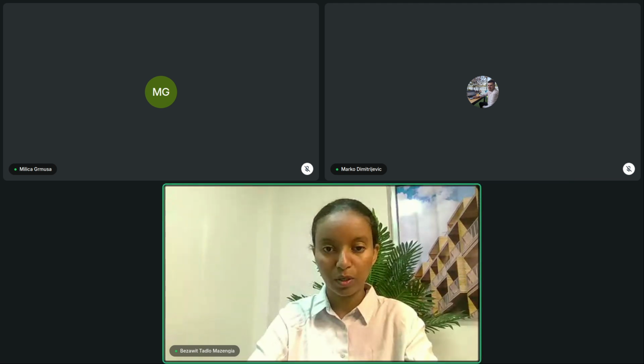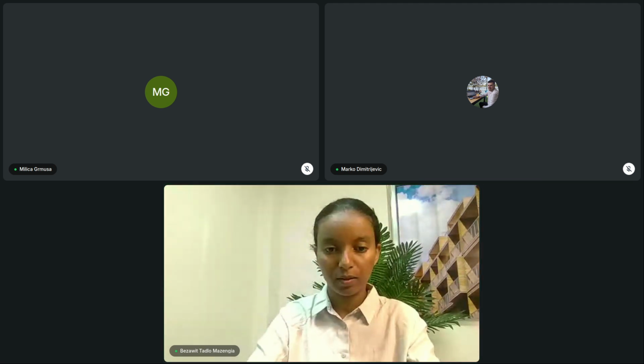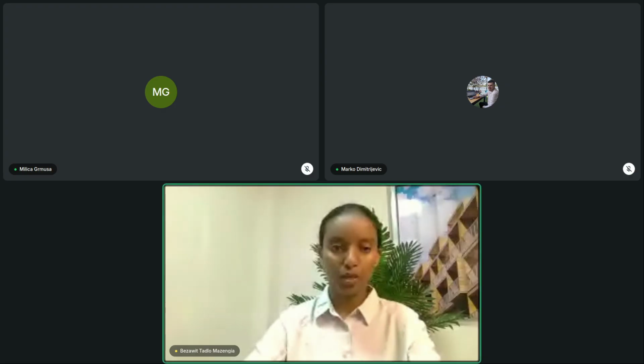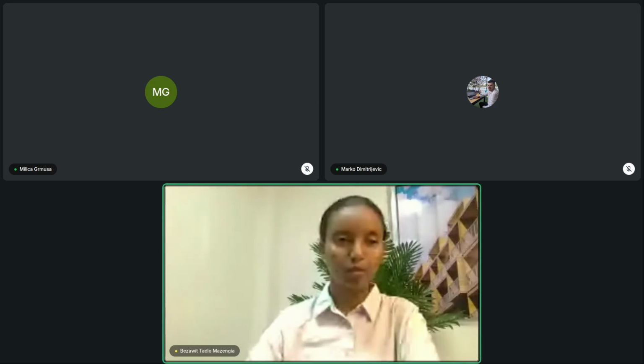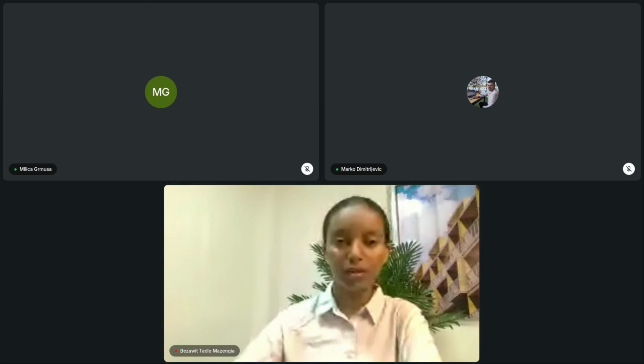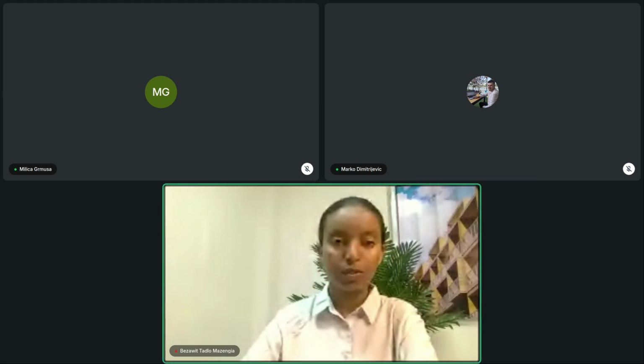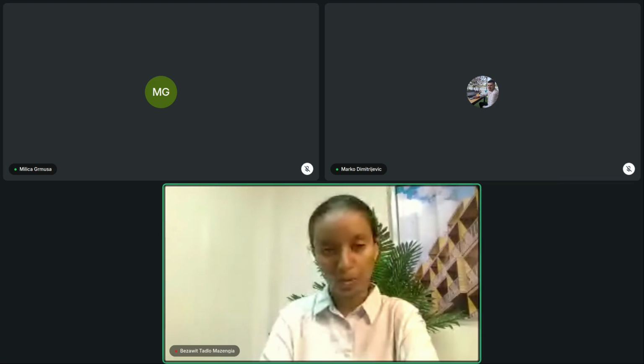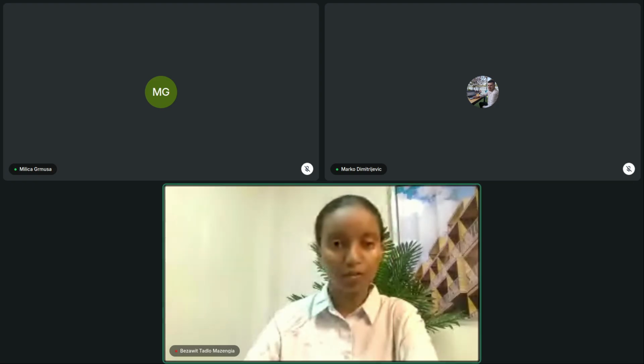Okay, let's go back to our PowerPoint. To summarize, if we want to do some design optimization based on spacing and distance requirements, this has a somewhat different effect on moment resisting systems and simple bracing systems. If we have minimum spacing, or small spacing, we will affect our brittle failure, or our timber member will be prone to brittle failures.